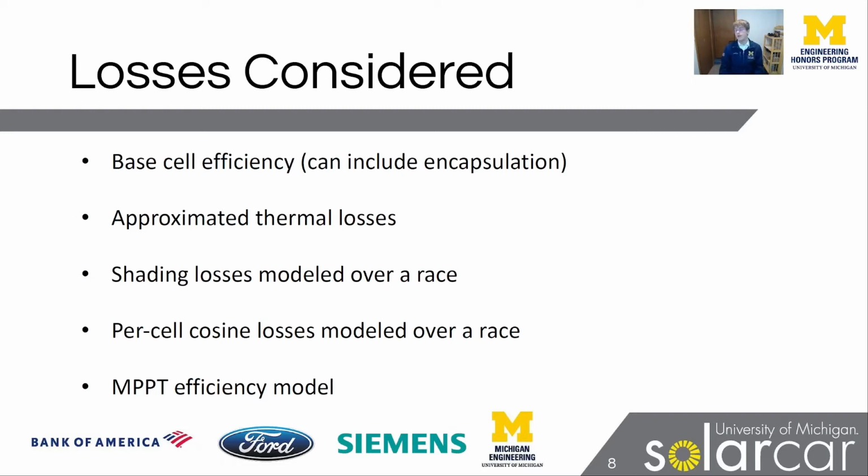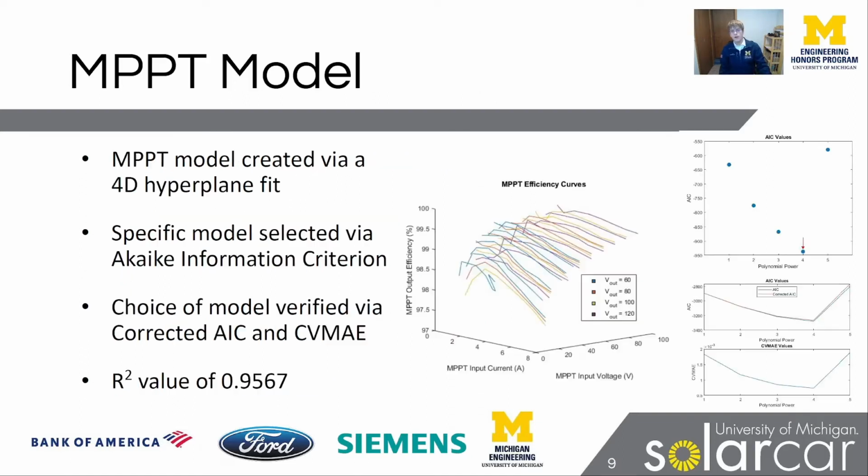We also have an MPPT efficiency model, which we can take a look at here. We worked with our MPPT manufacturer to gather these curves of how the maximum power point trackers on our car actually perform when they serve their important function of converting the voltage produced by the array to the voltage produced by the battery in order to charge the battery and power our motors.